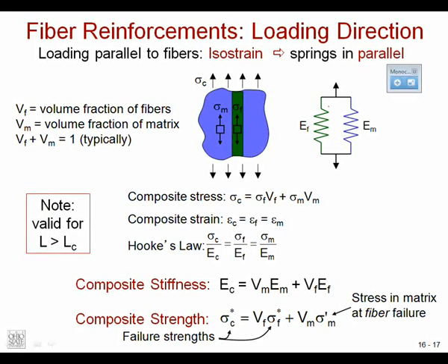And the derivation for these, we call these rules of mixtures, are here. But basically we're saying that the strain is the same in the fiber as in the matrix. Just like if we're pulling two springs apart, then they're going to go apart the same amount.